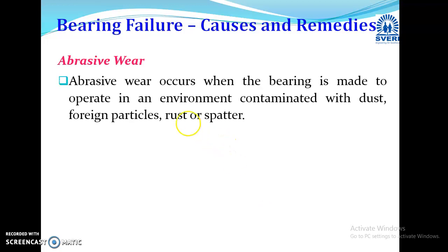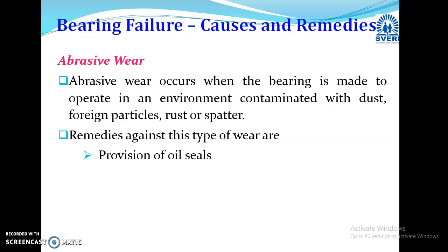Abrasive wear. Abrasive wear occurs when the bearing operates in an environment contaminated with dust, foreign particles, rust and spatter. These act as abrasive particles and wear the bearing surface. So this comes under abrasive wear. What are the remedies in these cases?